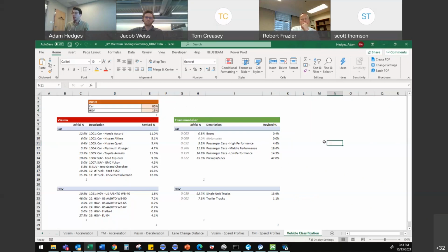And Jay is pointing out in the chat that KYTC has the VIN data. We were looking at the state, but you could narrow it down to county level. If you had a project that you felt was different, or you wanted to investigate that, you could certainly look at that in the scoping of a project, or even collect a vehicle classification count. And we have some images in the guidance document about the breakdown of where the different vehicle classes fall.